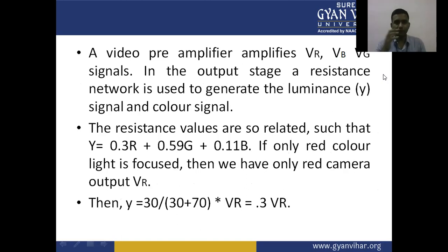A video preamplifier amplifies the VR, VG, VB three voltage signals. In the output stage, a resistance network is used to generate the luminance signal and color signal.